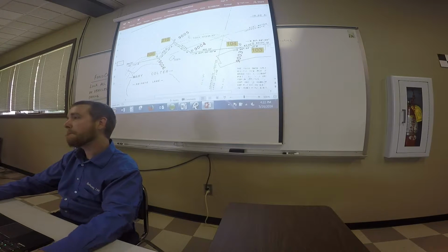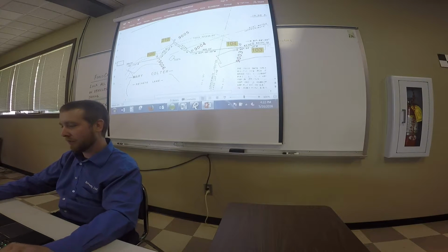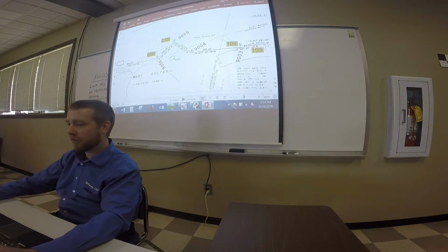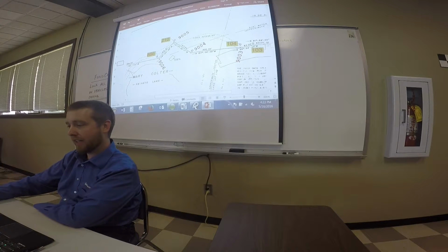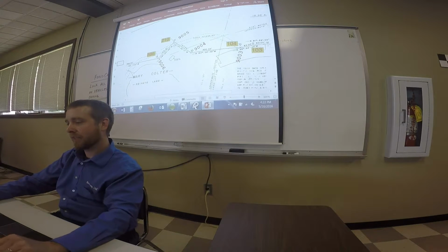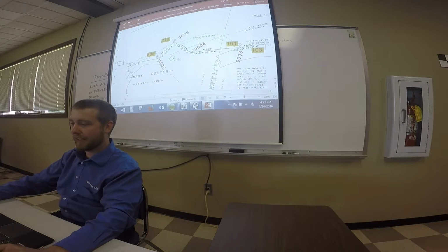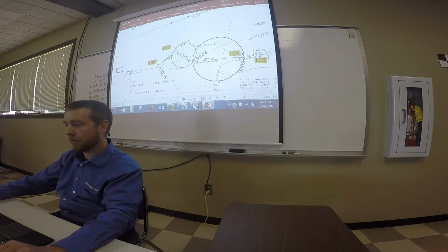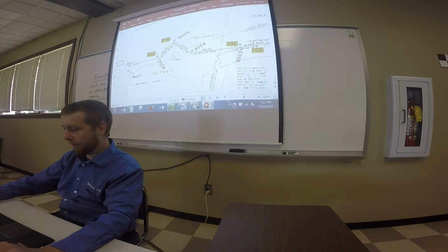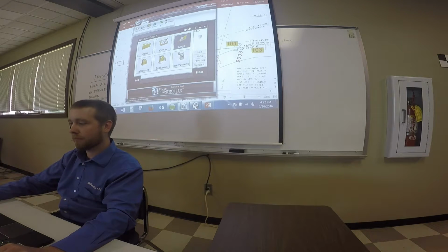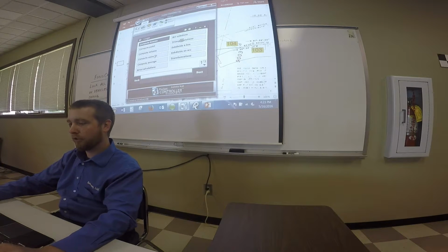Yeah, you calculate that turned angle on the other data and use it to create a new point on your data. Correct. So we know that 9,004 is what we're looking for. 9,005 is the same as 210. 9,006 is the same as 886. And we've already inversed 9,005, 9,006. We know they check pretty good. So now we're just going to turn that angle to find that pin. The way you do that, you get back into the data collector, go to COGO, go to Compute Azimuth.